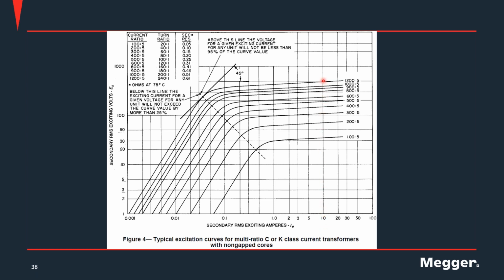You connect this to this point here, you look to the left, and this would be the allowable voltage at 20 times nominal for a 10% error. If you had 5% error, then you would come to your 5 amps here, because it's 20 times 100, 5% is 5, and then you would see here that your allowable voltage would be here on the left.